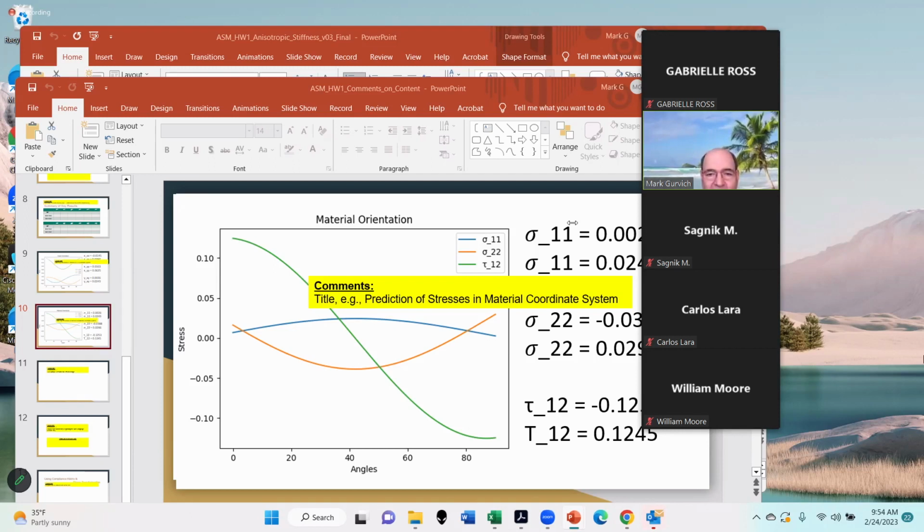In the control validation, are we just comparing results? Rishi asked a question: in the control validation, are we just comparing the result between variant 1 and 2? Yes, that's correct. You calculate epsilon sub x and epsilon sub y. In variant 1, you calculate epsilon 1 and epsilon sub x. In variant 2, you compare them, and theoretically results will be 100% the same. If they're the same, you could say, aha, at least one check mark is satisfied. It's not the only check mark, but at least one is satisfied. So it's a very good check. Answer is yes.